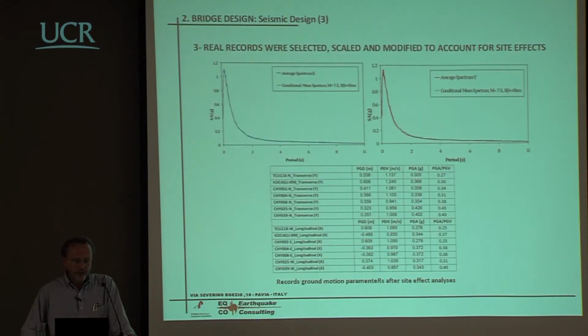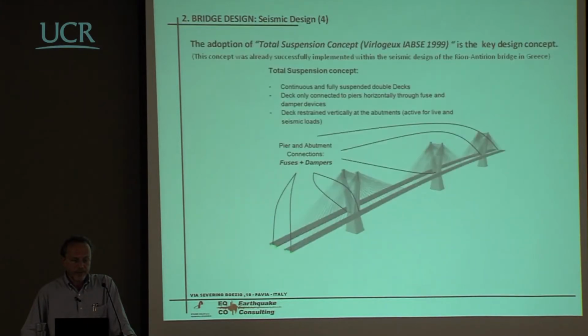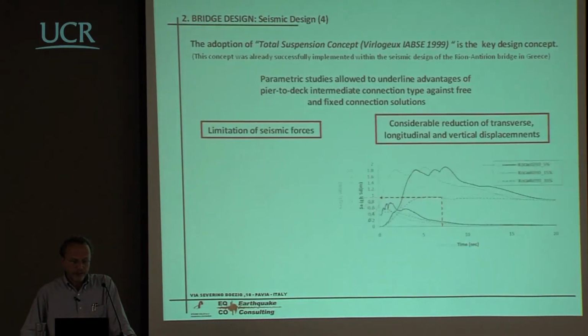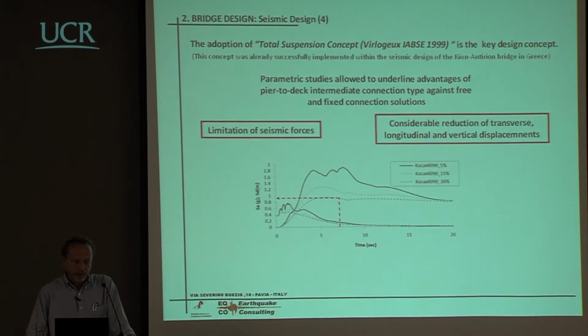And then you produce your spectral shape, and you go through some complete analysis, and you may have a look at this spectral shape here. These are displacement spectra, and this is the displacement spectrum for 30% equivalent damping, and this is the final period of vibration.